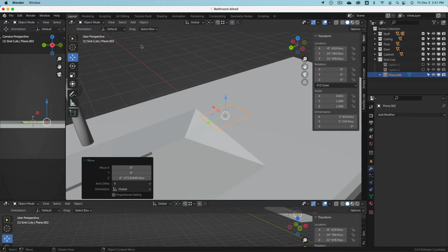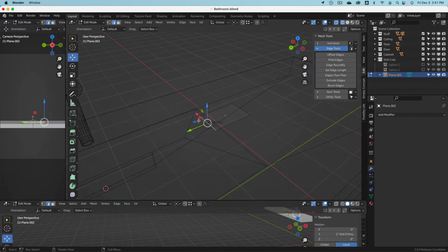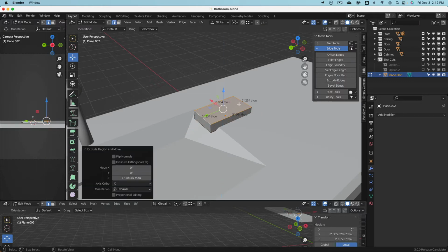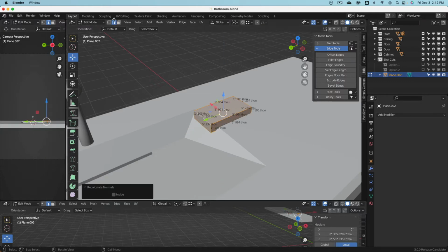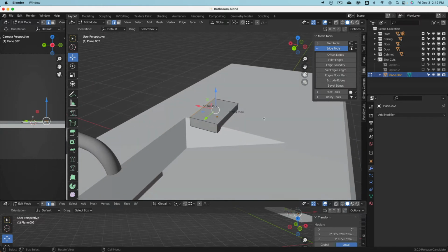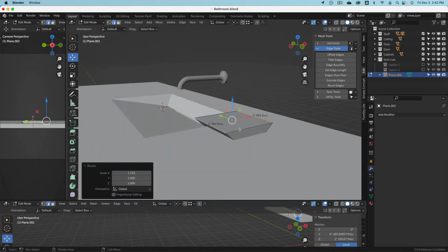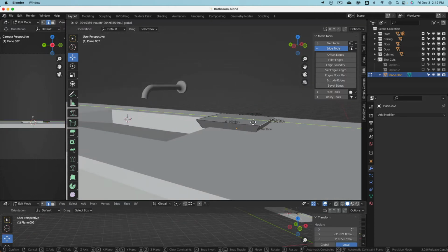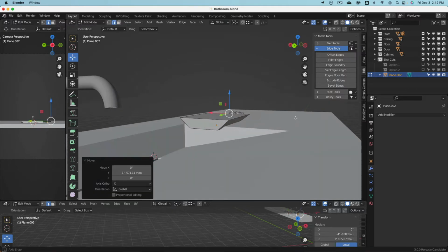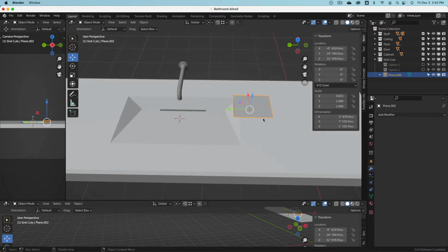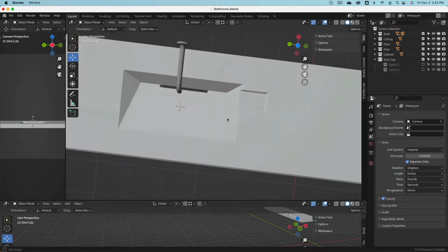Okay. Going to edit mode via Tab, Z. I need to select this edge, move this over. A, E, A, and Shift N. I just do this by default already. And then these two faces here, I will select, S and X, and chamfer it nicely. Select this edge and there. I said chamfer the edges, I meant more move the edges so these sides are angled. Cool. And then this flap, drag in there.